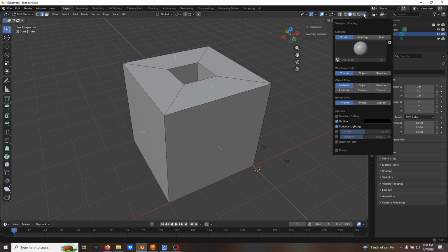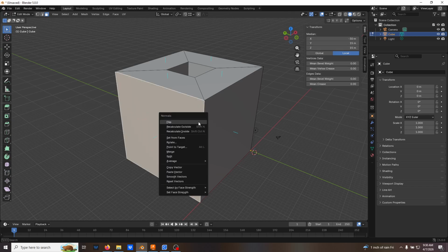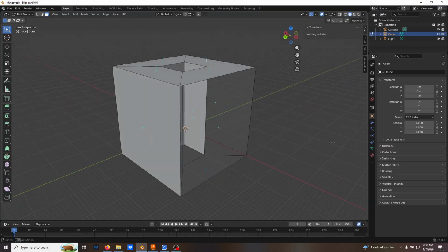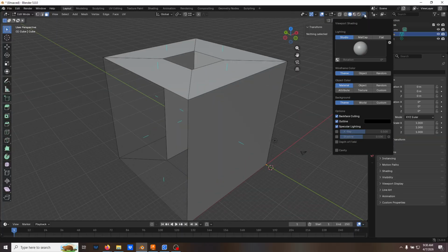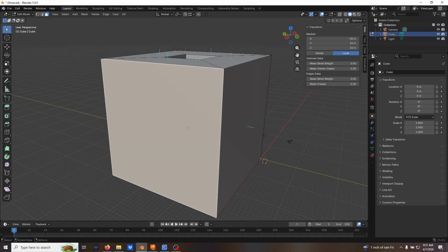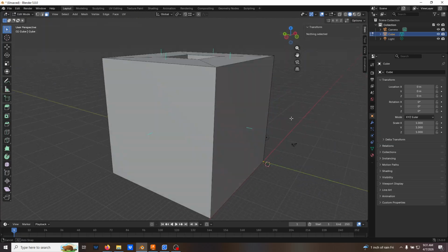Also, I'll use this a little bit later. There's also a backface culling tool which will show if your faces go backwards. So if I select one of these faces, I'll go back to face select, and I'll use Alt N for the normals menu. If I flip it, since I turned backface culling on, you don't see that face there. I'm going to turn backface culling off for a minute, but I'll use that later. These are just different ways to check your face selection. So I'll go back here, Alt N from the normals menu, and then I'll flip it. Okay, so then I have my part.